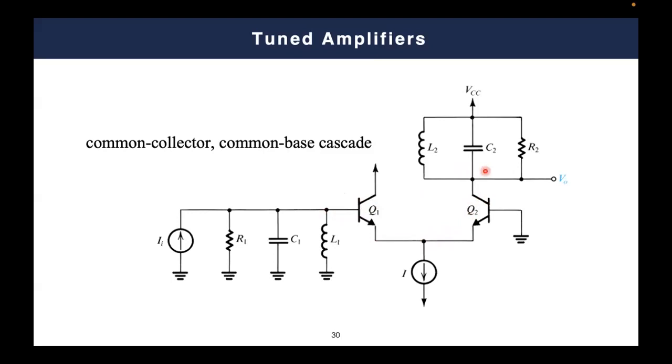So again, you are playing with the same trick to isolate the input and the output so that you somehow eliminate the effect of the parasitic capacitance. For example, here you have a parasitic capacitance with the VDD or the VCC, and here we have also a parasitic capacitance with ground. So of course, you still have a capacitance effect, but it is no longer linking the input to the output.